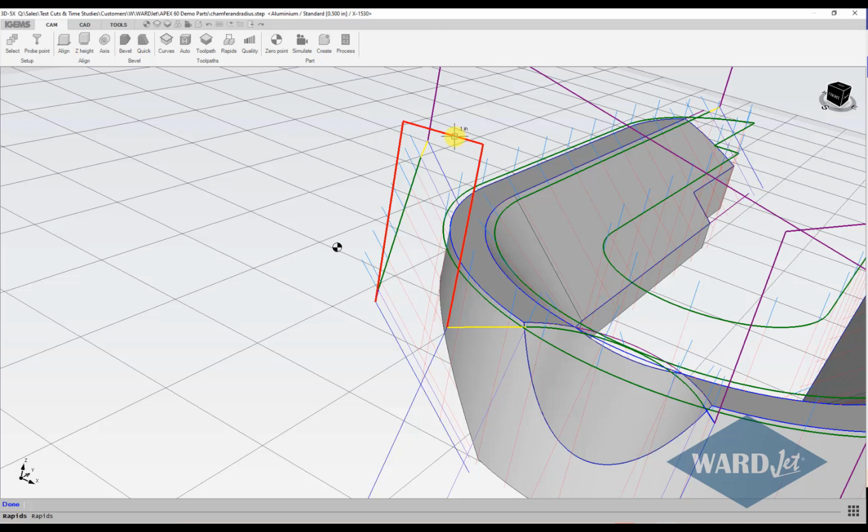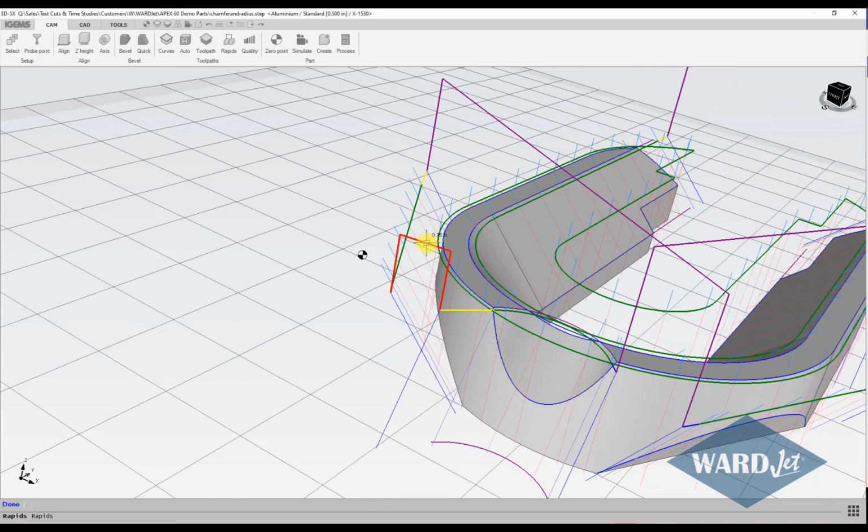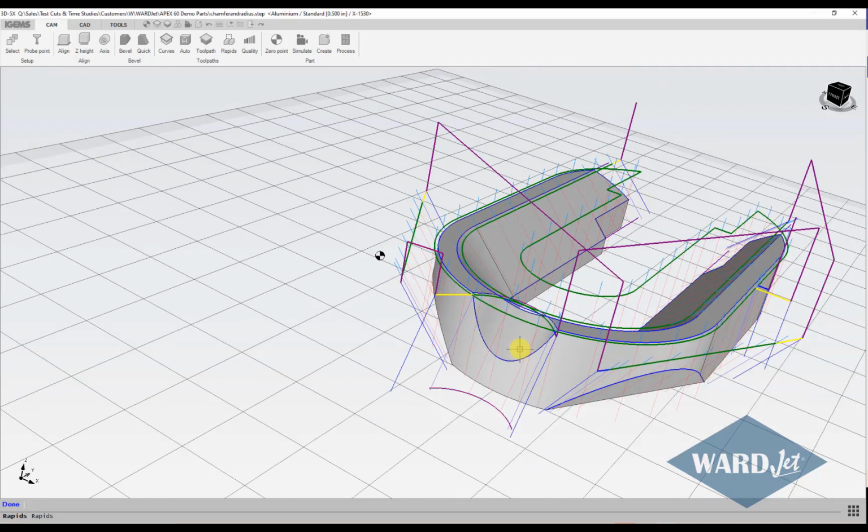You can click on this height button here, and when you hover over this, that's 1 inch that's shown there, that's 1 inch from the table, so a 1/2 inch lift. So if I change that to like 0.75, be careful on that one, 0.75, then it'll do essentially a 1/4 inch lift going from here to here.